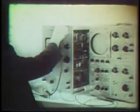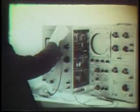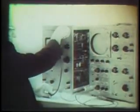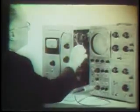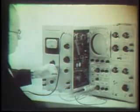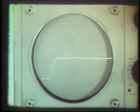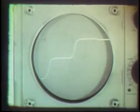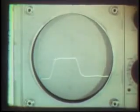A good way of checking if the line is properly terminated is to feed in a fast rising wave while viewing the results with an oscilloscope. When the line is properly terminated, we will see only the applied signal. If the line is not properly terminated, we will have reflections which will appear on the scope. With the line open, the display will look like this. If there is a short, the display will appear this way.